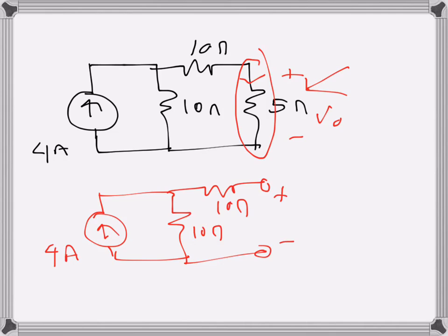So what is the open circuit voltage in this case? Now since we have this one open, there is no path for current conduction in this direction, so the current here will be 0. So the drop across this 10 ohms resistance will be 0 as well.